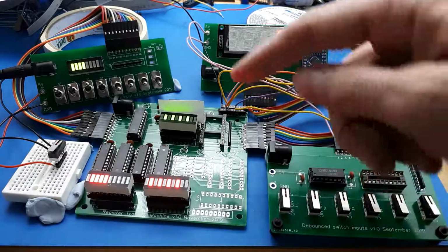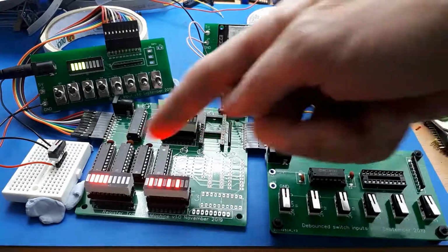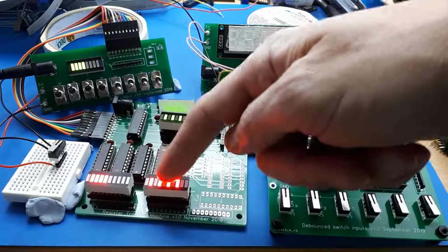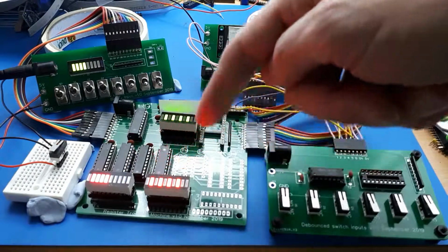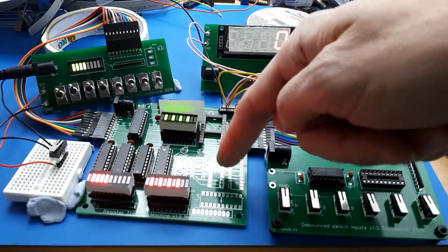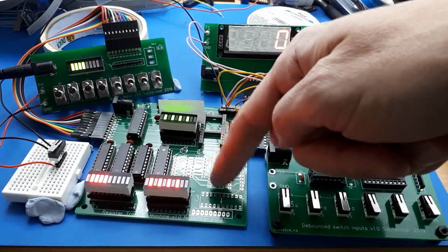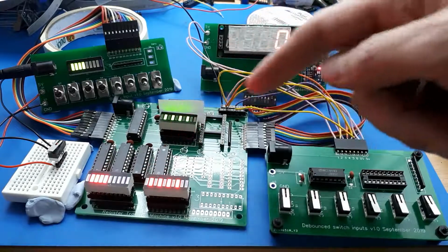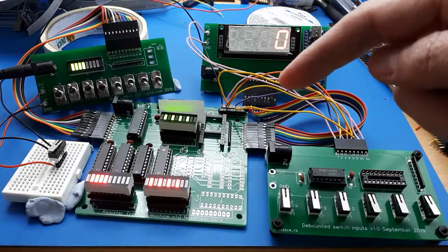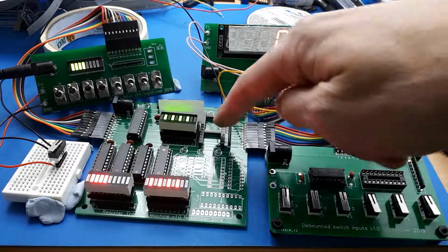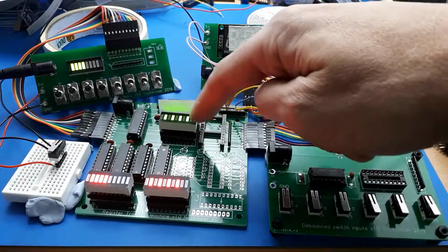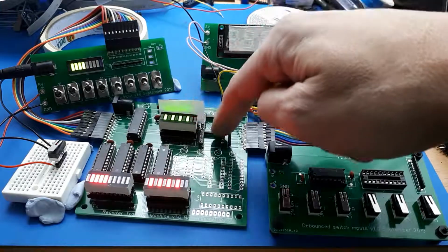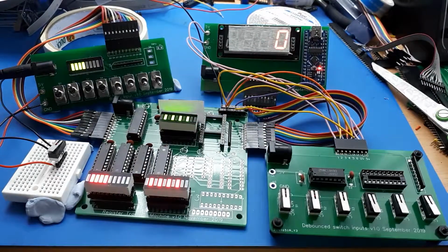Or I could have an ALU, which combines some data. That's what I've not quite implemented yet. So we'll be able to take this value and this value, combine them together, and make them appear in my third register, register 3, which I haven't done yet. So we might be able to add these 2 numbers together, or subtract them, or combine them in some other way. Also, I've got a slot here for a memory chip, because this register is a memory pointer register. It's pointing into that RAM. So I think I'll have a go with that one next.